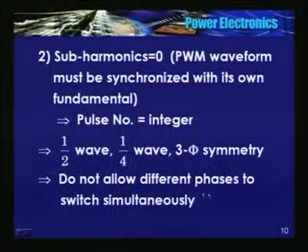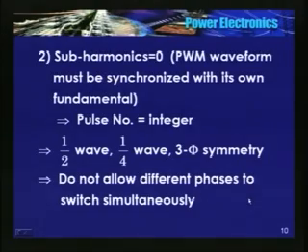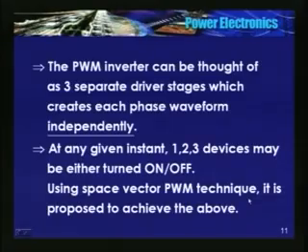We took a sine wave and compared it with the triangle. It may so happen that the upper phase A device may be switching along with phase B and along with phase C. So, at any given instant, either 1 or 2 or all 3 switches may be either turned on or off. So, one of the features that I told you is, do not allow phases to switch simultaneously. Whereas in the sinusoidal PWM technique, you cannot ensure this.